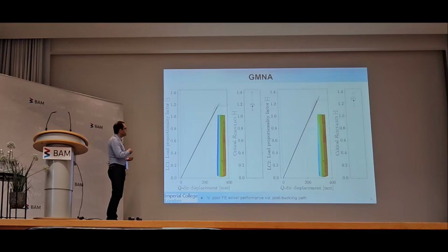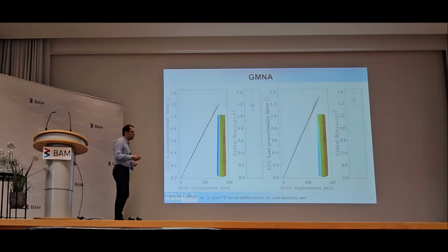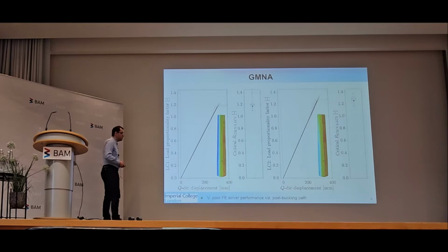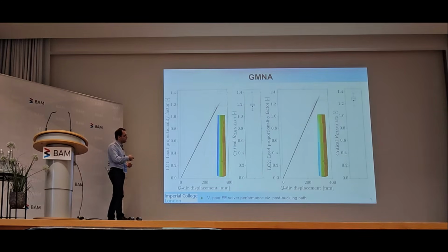I'm still fighting with Abaqus to do the same thing that I was fighting with it to do 15 years ago. There is clearly no development being done on the solver side anymore. It's pretty much set in stone. All of these ANSYS and Abaqus tools, they do change, but they just look fancier. But the underlying solver hasn't changed in two decades, at least for buckling. This should give you a post-buckling path that sort of drops down and then begins to do this. But in all of the submissions, nobody gave a correct post-buckling path, not even me.